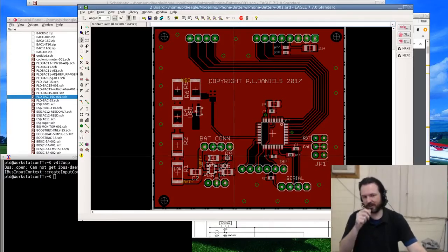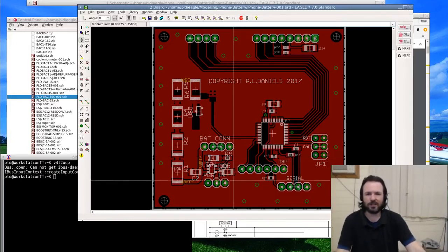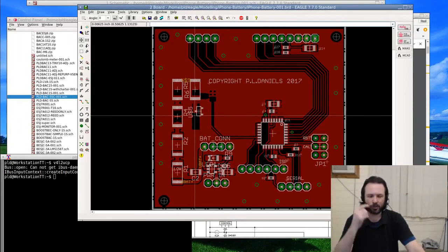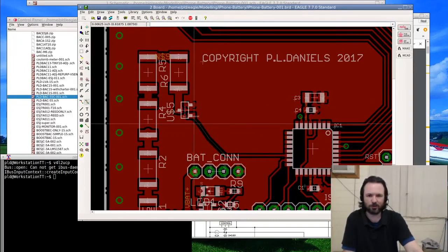This is going to be for an iPhone battery like this, so I can charge, discharge, and monitor what's being used, like the milliamp hour capacity, which just reminds me now that I haven't put any current sensing in this. Hopefully I'll make it so that the microcontroller can talk with the battery gas gauge, and then I can get things like even just a serial number. But I suppose if I get one bit of information, I'll pretty much get it all. So I've completely forgotten about current sensing.